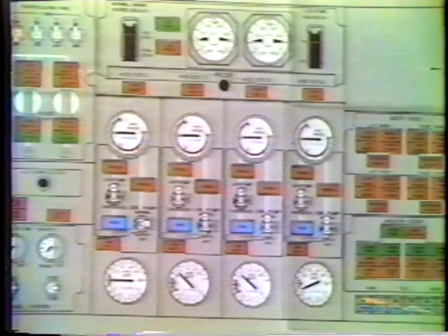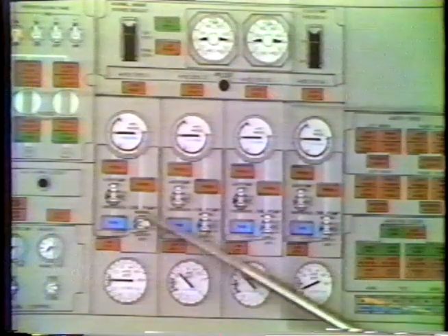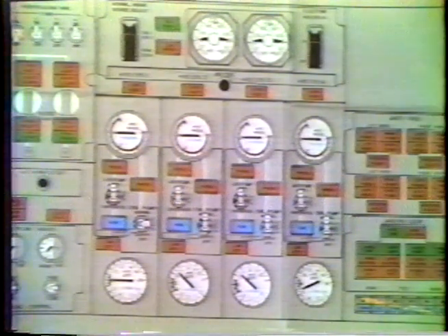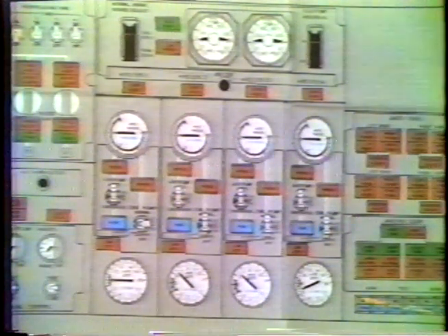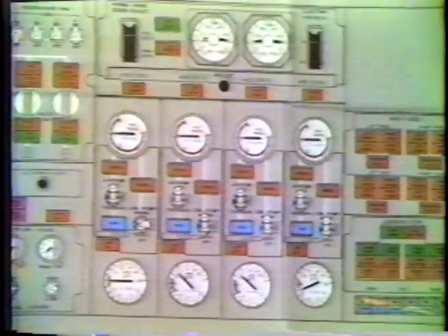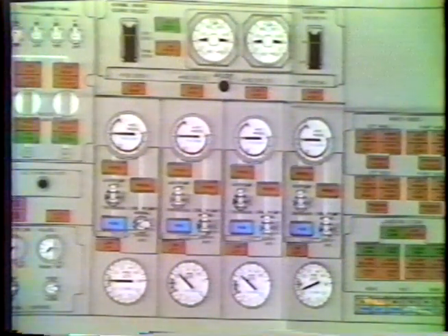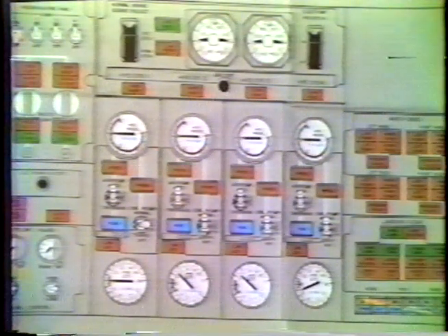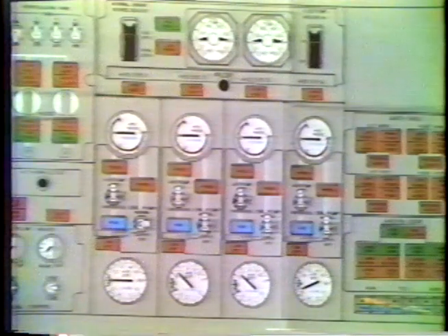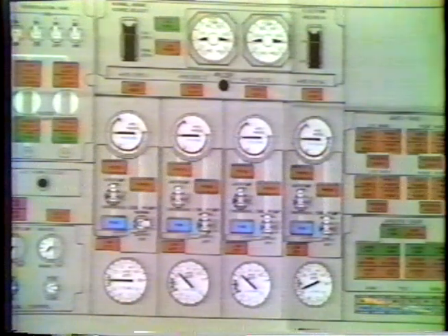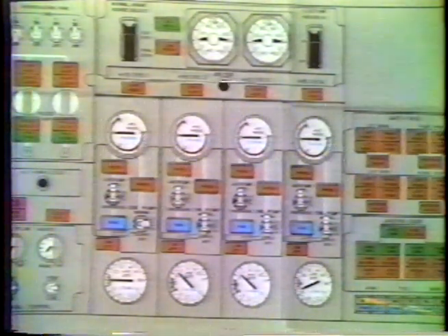pumps. On systems 1, 2, and 3, we have 2 pumps, the air pump and the engine pump. On system 4, we have 3 pumps: the engine pump, the air pump, and the electric pump for ground operation. All of these pumps dump into the same case drain line, which in turn goes to its respective fuel tank, is cooled by running through the fuel tank, and then returned back to the reservoir of that hydraulic system. This is the case drain line. The overheat and the temperature are looking at that case drain line.